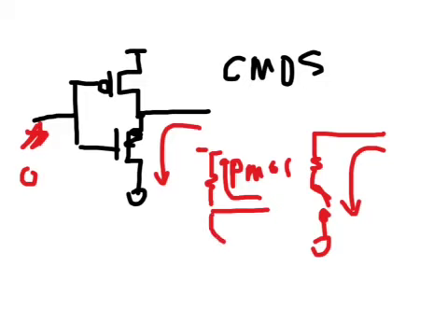And because in the pull up and the pull down state, there is no continuous path from VDD to ground, power is not consumed in the CMOS circuit when it is holding a steady state of either logic 1 or logic 0. So power is only consumed during the switching operation, in the briefest moment when both channels are partially on, when they transition from a pull up to pull down state.